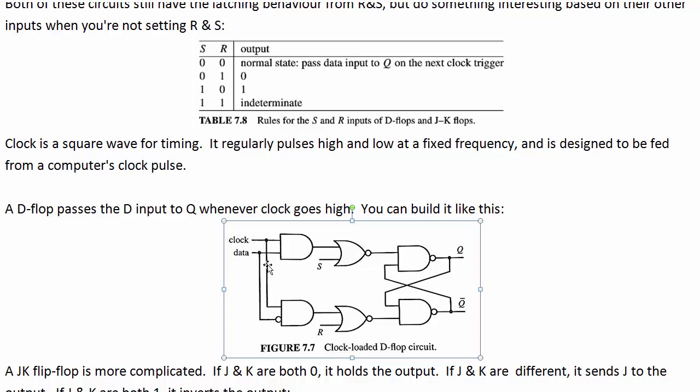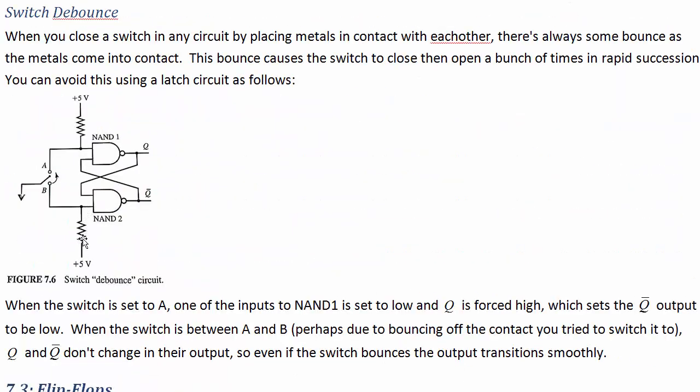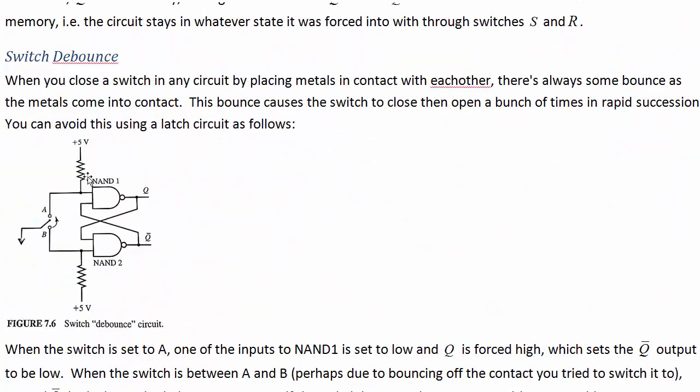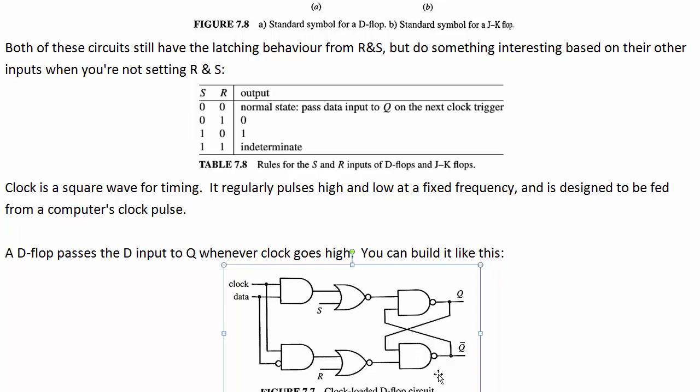When clock is low, both of these are outputting a 0, and so NOT 0 is 1. We're getting a 1 to both of these inputs here, which is just like when we were pinning the bottom parts and top parts, the other inputs to the latch, to a high. Okay, so we've got 1 at both of those inputs, and that means it's just holding its output.